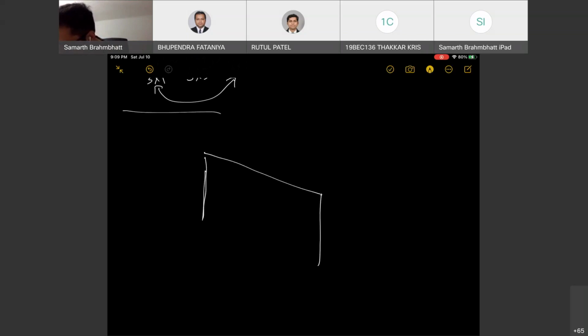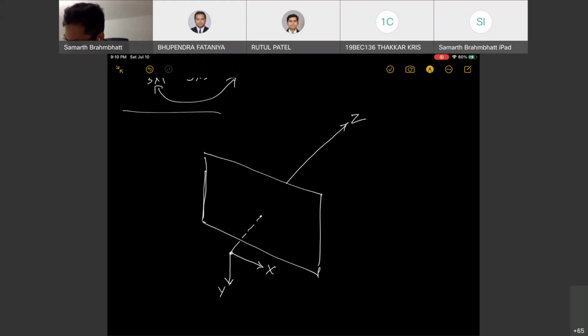So here again we have our image plane, and like always we have our camera center, and as I mentioned, the x-axis usually goes to the right, y-axis goes down, and then your z-axis typically goes out of the camera, right? So this is your z-axis, and the point where this z-axis intersects my image is called my cx, cy, which are part of my intrinsic matrix.